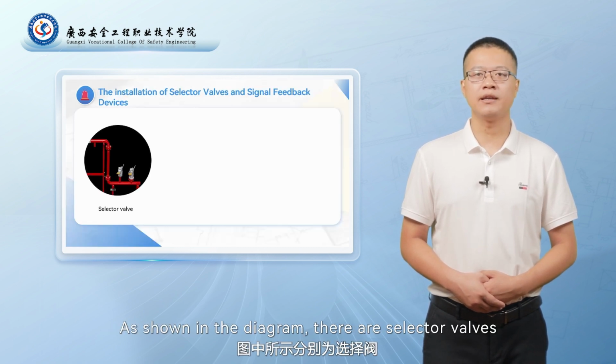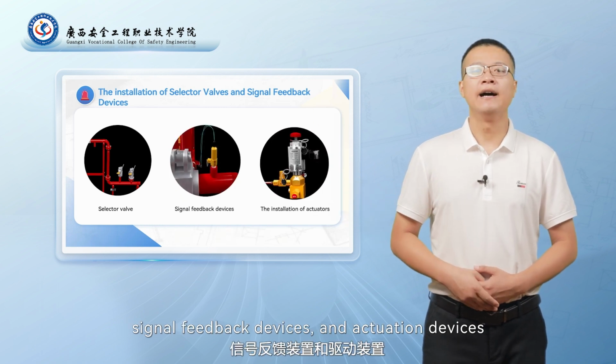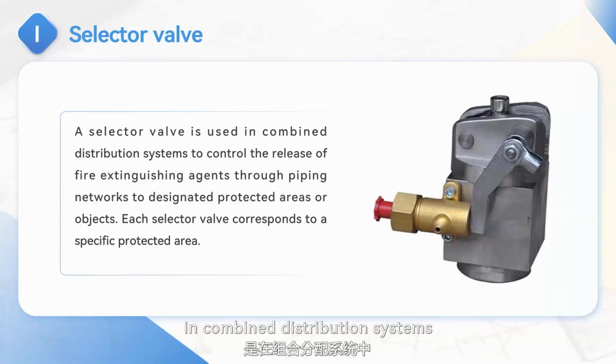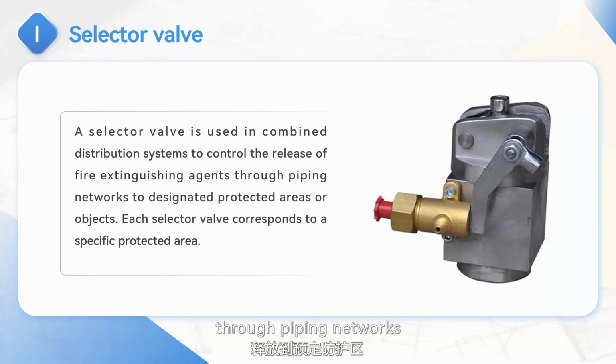As shown in the diagram, there are selector valves, signal feedback devices, and actuation devices. What is a selector valve? A selector valve is used in combined distribution systems to control the release of fire extinguishing agents through piping networks to designated protected areas or objects. Each selector valve corresponds to a specific protected area.